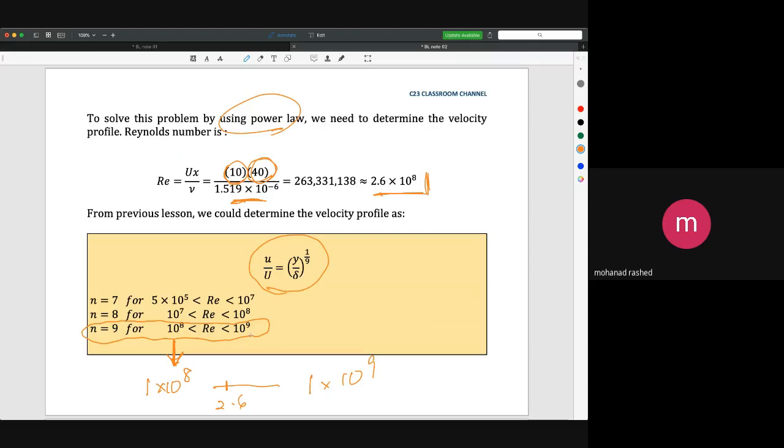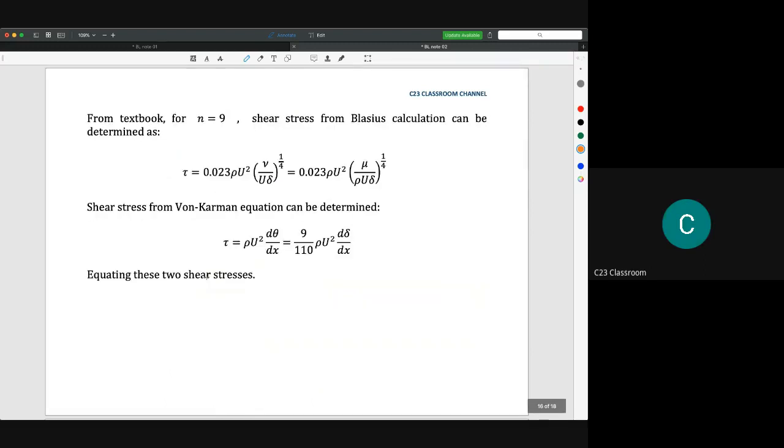So, doctor, in this case, we should see these calculations or these ratios. Our velocity profile will depend on this ratio. Yes, for the turbulent. Okay, you need to choose. But normally, if you don't have it, 1 over 7. Yes. Okay. Thank you.